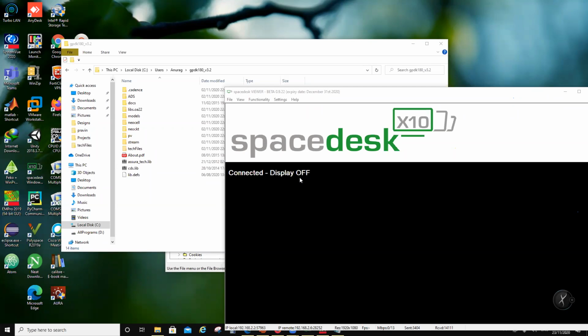Even if I have to declare a variable which is tunable, I have to use something called param or a keyword like that, and then put in brackets whatever you want to vary. Or in your Analog Artist, you have to read that variable and set the values for the variable. In ADS, it becomes very easy. Everything is like a slider. You declare a variable, slide the variable, and it will change automatically in the circuit, and you will see the results. So things which are easy to do in ADS, you will struggle to do in Cadence.